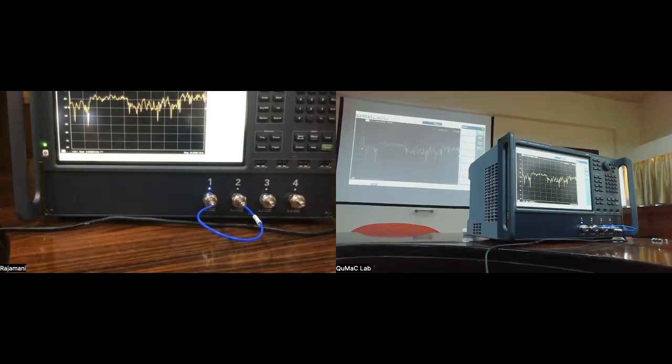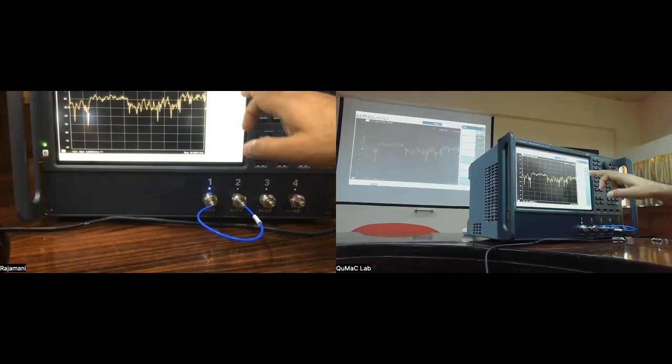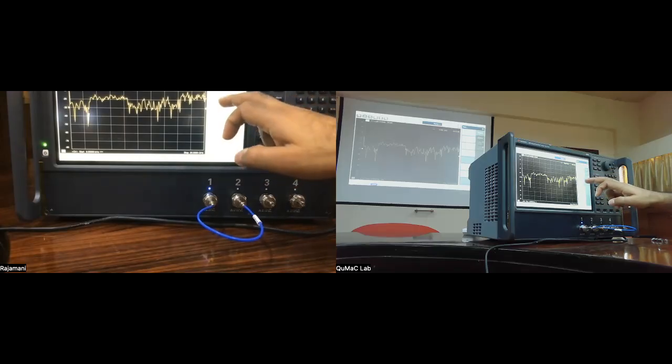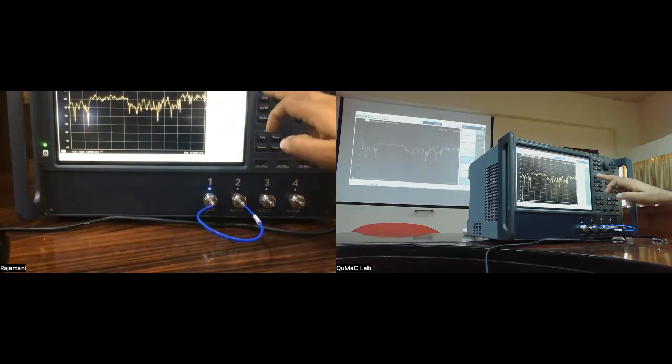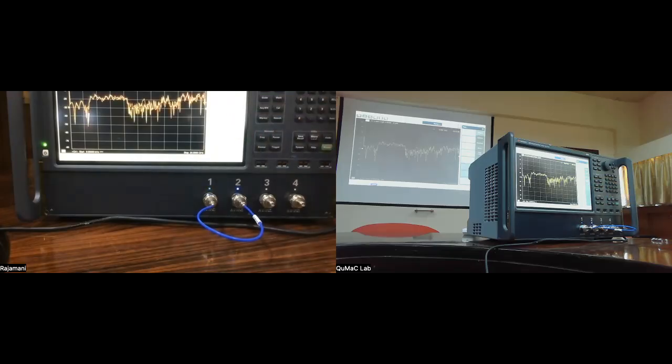So in general, for a lossy medium, your incident power should be equal to the absorbed power plus the transmitted power and the reflected power, right? So everything has to add up. For a lossless network, of course, what's going in has to come out from somewhere. So either from the reflection or from the transmission, just in the case of a two-port scenario. Okay. Now, let me put this to memory and compare this with the reflection on the other port.